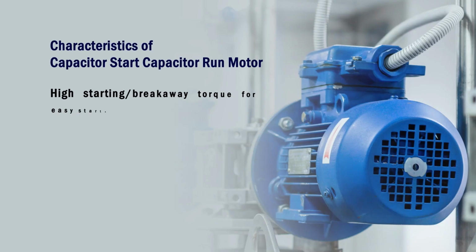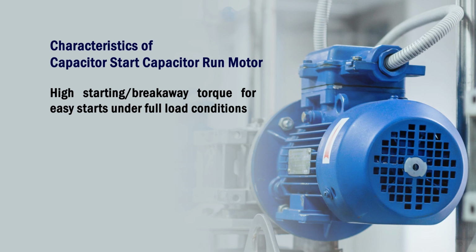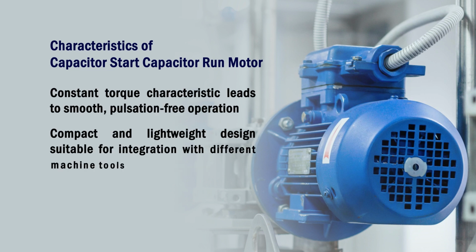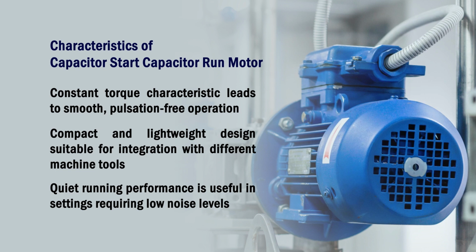Characteristics of capacitor start, capacitor run motor. High starting or breakaway torque for easy starts under full load conditions. The improved power factor and higher efficiency due to permanent phase correction from the running capacitor. Next characteristic is the constant torque characteristic, which leads to smooth pulsation free operation. It is compact and lightweight design suitable for integration with different machine tools. It is having quiet running performance, which is useful in settings requiring low noise levels.